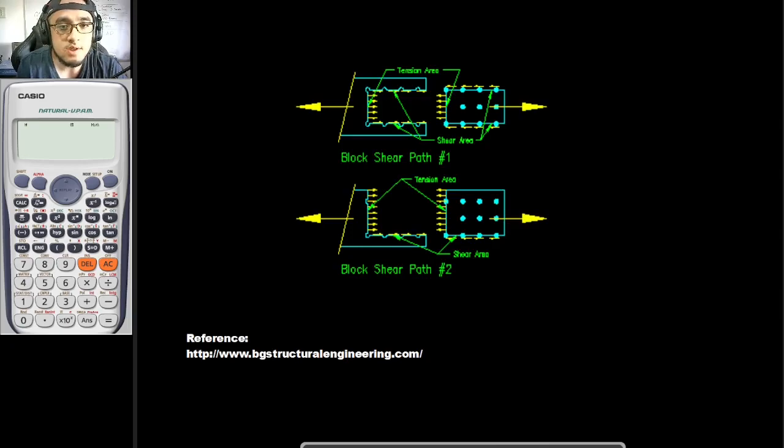Oh, by the way, this is the manner in which it would fail. In reference to bgstructuralengineering.com, these are two of plenty of ways a certain structural member would fail through block shear. Let's say we have this tensile load. It can fail in this manner, whereas this part right here is disconnected from this part right here. As you can see, this certain area right here is perpendicular to your line of action, meaning this area is your tension area. That is from your mechanics of deformable bodies or strength of materials subject.